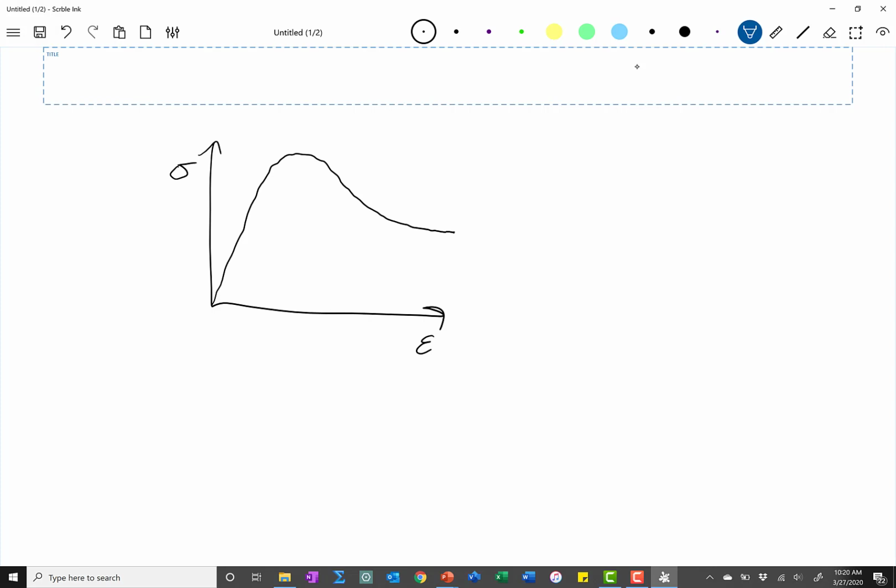If I were to load up in triaxial loading a very loose specimen of the same soil, it might show something that looks like this. So that would be like strain hardening behavior. But you'll notice that whether the soil had a high relative density or a low relative density to begin with, at high strains, they all go to the same place. And so what that means is the fabric of the soil becomes so disturbed that the initial relative density or the initial state of that fabric does not matter. And so this is why we call this the critical state,